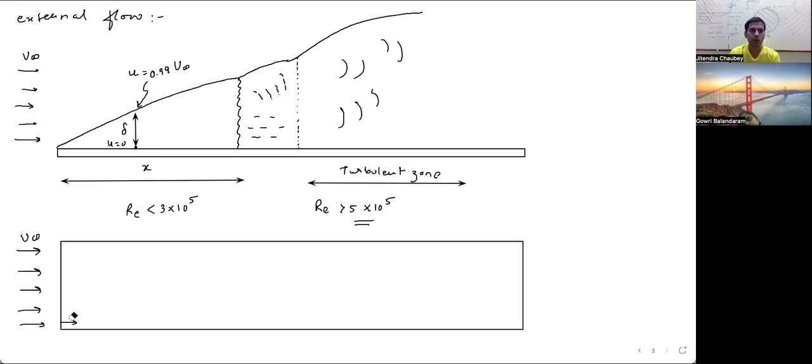So to understand it, we can say that excluding the fluid near the surface, all the other fluid will have velocity equal to the entrance velocity. And as the fluid propagates, this phenomenon will keep on increasing. This curve will try to bend more. You will see that the span over which the velocity was the same will reduce now, because it will eventually retard the adjacent layers.